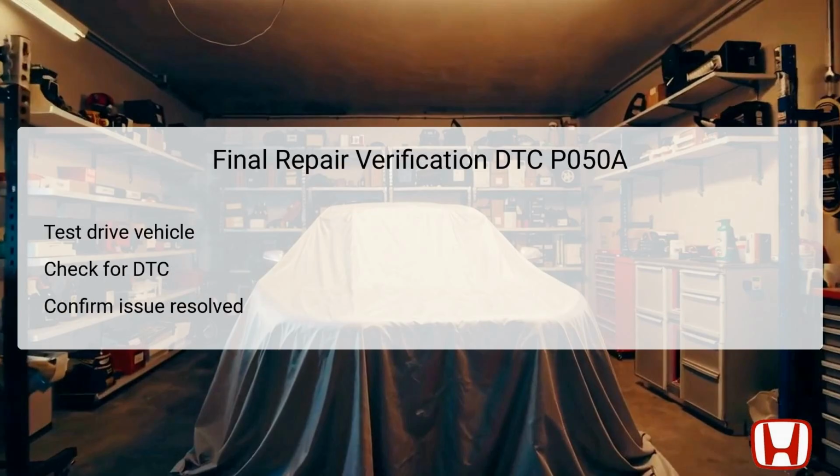After completing the required repairs based on the P050A troubleshooting process, it is essential to conduct a final verification to ensure that the problem has been resolved. Start with a test drive of the vehicle under various operating conditions, monitoring its performance closely for any irregularities. During this test drive, pay particular attention to the idle behavior to see if any erratic performance issues resurface.